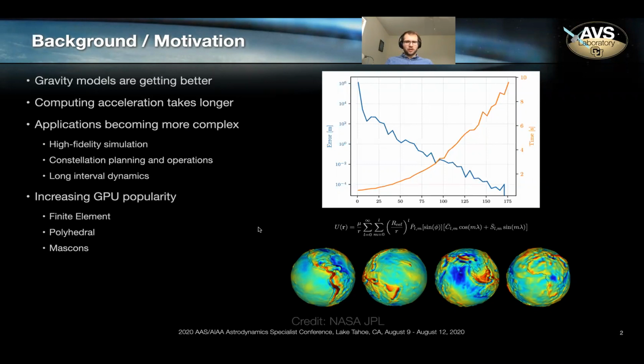applications. But there is one downside to having a higher fidelity representation of the field, and that's they're expensive to extract an acceleration from. As the fidelity of your spherical harmonic model increases, the number of compute terms, the number of operations needed to extract an acceleration grows exponentially. And that's problematic as our community is growing increasingly reliant on simulation, and to become bottlenecked by the fidelity of the gravity model forces us to trade between simulation speed and simulation accuracy.